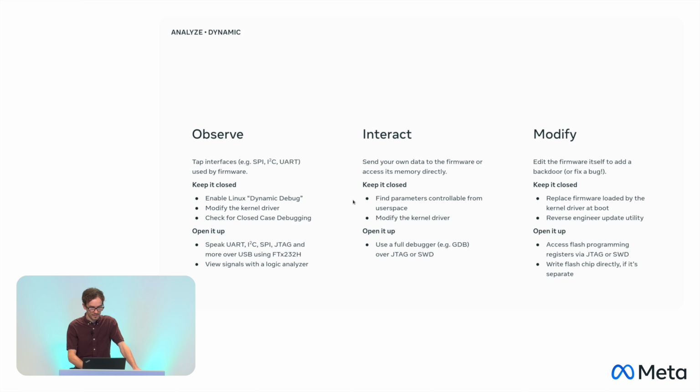And then in many cases, that's enough to just call some vendor-specific manufacturing test function you found that was never supposed to be there, but it is, and calling that lets you make the firmware do something bad, run code in the firmware, whatever your goal is. Sometimes you can trigger that from the kernel. And then if you want to do it physically, then most CPU cores, even firmware CPU cores, have interfaces like JTAG, which let you run hardware debuggers, and you can use tools like OpenOCD for that, for example.